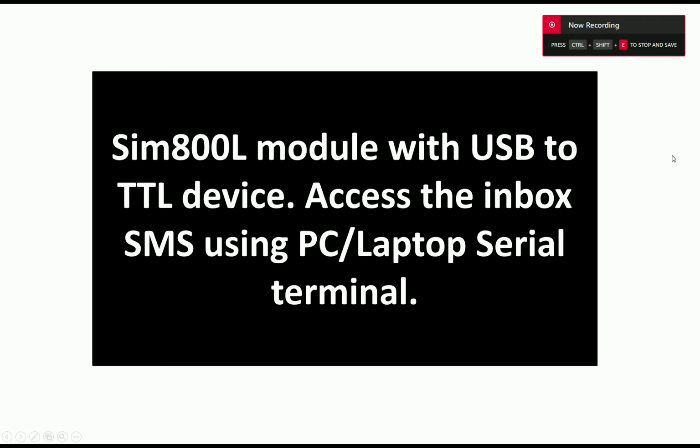In this video, I'm going to show you how we can use a SIM800 module with a USB to TTL device, and then I will show you how you can access the inbox SMS using a serial terminal on your PC or a laptop. So this will give you a direction in how you can program this using any microcontroller. First of all, we will understand what the commands are and how they are used using a PC. And this will also verify if your SIM800 module is working fine or not.